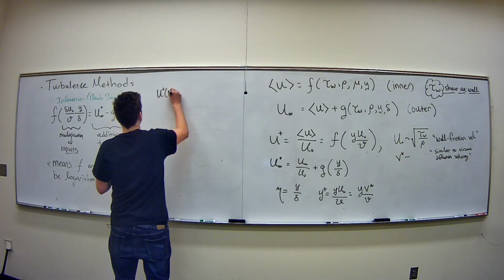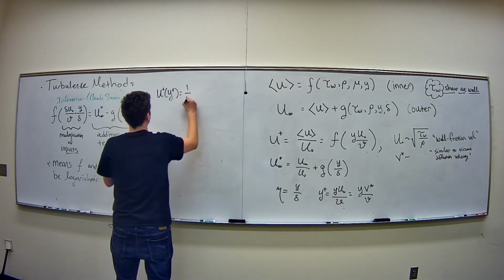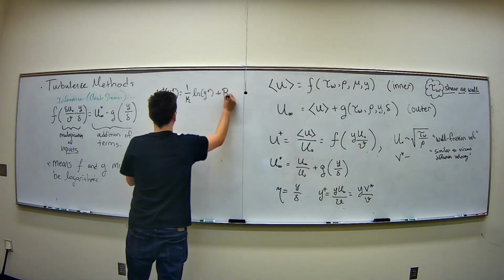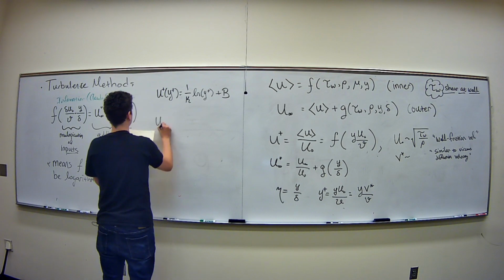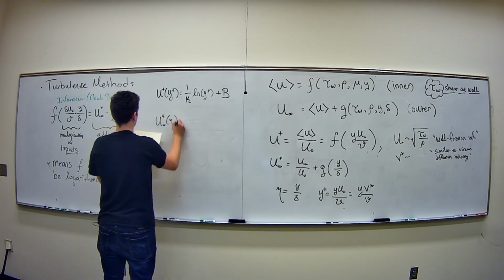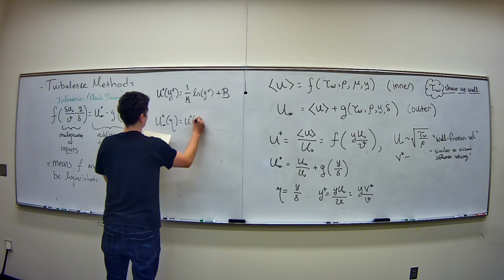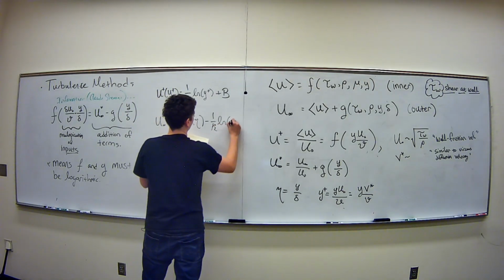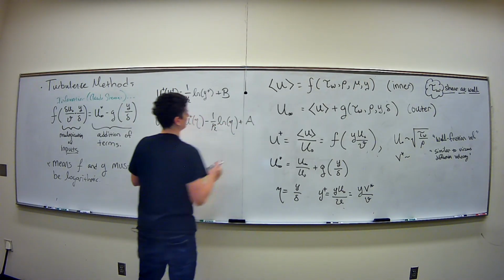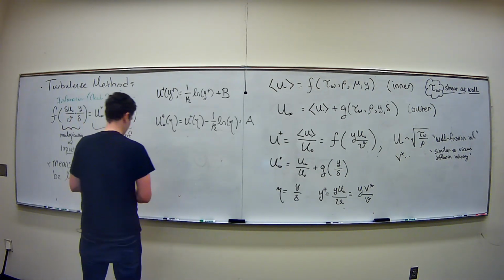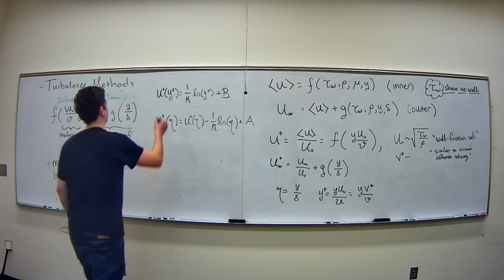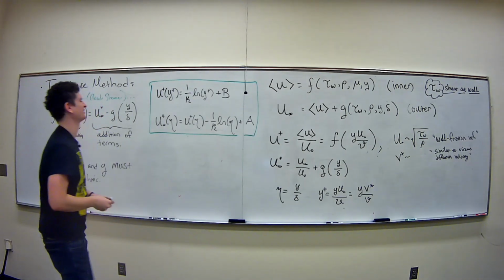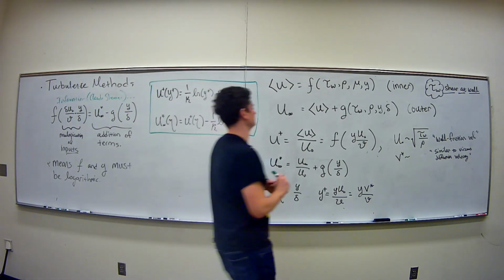So then this is your classic result. This is a kappa, and you get these laws of the wall. These are the laws of the wall you get from turbulent flow, and it's the only main result I have for you in this lecture: through this relationship of shear stresses and turbulent shear stresses, you can at least show this just because of a matching condition.